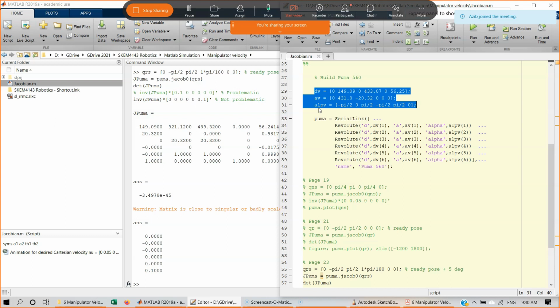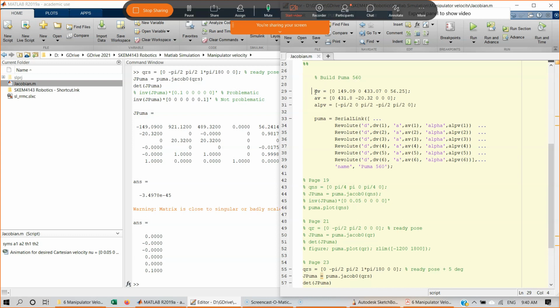So first, for every link of our robot arm, we would establish a coordinate frame according to the DH representation. There's an algorithm, right, which will be given for your test and exam. Using that algorithm, you will establish one coordinate frame for every link of your robot arm. From the established coordinate frames, you will come out with the DH parameters: d_i, a_i, alpha_i.